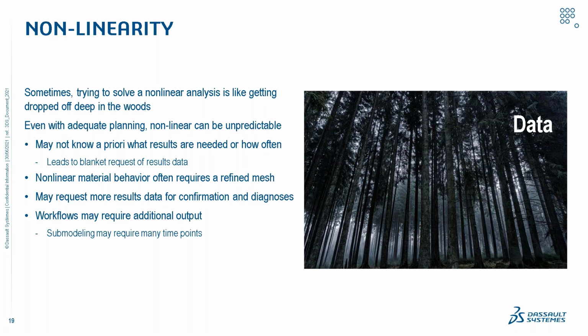You may request more results data for confirmation and diagnoses that you wouldn't necessarily have to do in a linear analysis. And your workflows may require additional outputs. As mentioned before, if you're running submodeling, you might have many time points that you require during that analysis.